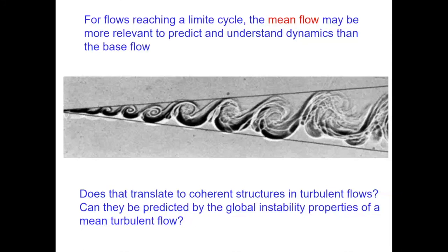Quick and dirty because we are not going to do a statistically consistent treatment of the turbulence. We're going to go for a rough eddy viscosity model. The idea is that we're going to separate in a triple decomposition, as proposed by Reynolds and Hussain in 1972. In this triple decomposition, we have a time-average flow U, we have a coherent fluctuation U hat, and we have an incoherent fluctuation U prime.